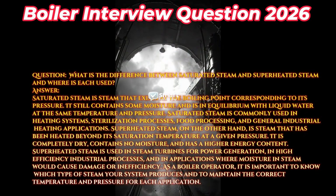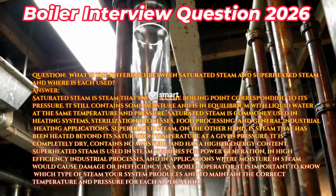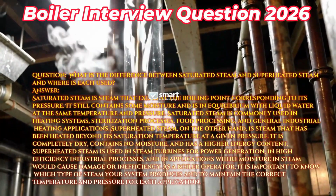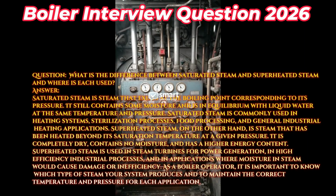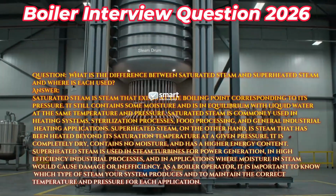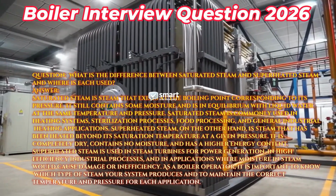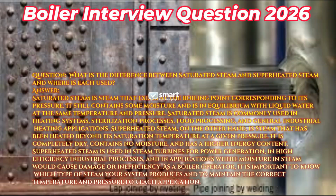Question: what is the difference between saturated steam and superheated steam and where is each used? Answer: saturated steam is steam that exists at the boiling point corresponding to its pressure. It still contains some moisture and is in equilibrium with liquid water at the same temperature and pressure. Saturated steam is commonly used in heating systems, sterilization processes, food processing, and general industrial heating applications.